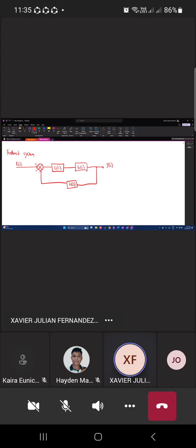Okay. So what is the closed loop transfer function? That's equal to Y of S over R of S, which is G of S, no? Let's not use G of S. Let's use GE of S, since this has not yet been synthesized into one. Let's just call that GE of S, all over 1 plus minus GE of S times H of S. Okay.